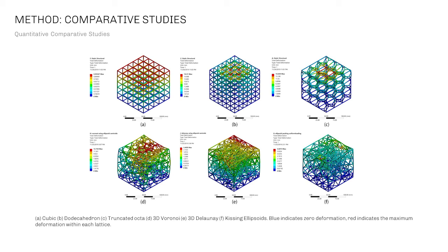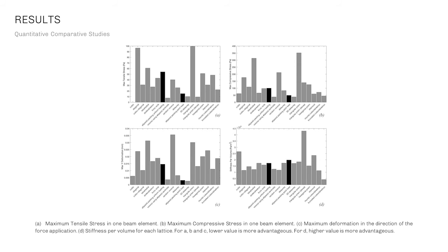The maximum axial force and directional displacement data without this length correction are also reviewed to get a general sense of the performance of the lattice. As the interest group, 2 ellipsoid packing lattices are tested, one generated with a uniform loading condition input and the other with a point loading input. The result illustrates how our lattices perform in stress, deformation, and stiffness against the control lattices generated with other algorithms.